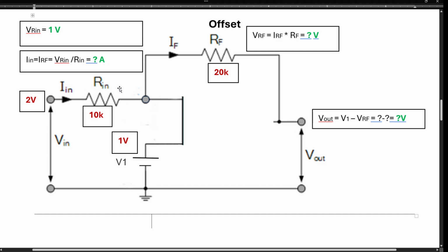With the plus and minus, this is the more positive side, this is the more negative side, so the current flows that way, as the arrow shows. If this voltage is greater than that voltage, because that can change, then of course the current is going to go that way. Always have to consider the direction of the current, because that is going to show you the pluses and minuses on the devices, especially this one here. All right. So now we established that the current flows this way because this is the more positive side of the resistor. So it is going to continue flowing that way.